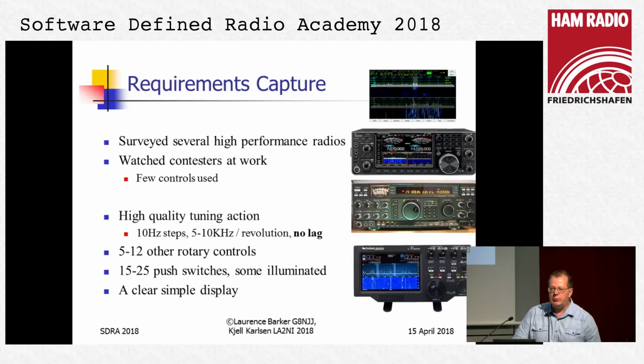So what I did was to watch a contest through the 24-hour SSB field day. And he used almost none of the controls on his FT1000. There's a whole load there. He used the tuning knob, obviously, very occasionally the receiver independent tune, and quite often the variable passband tune to get rid of interference, either at the bottom or top edge of the signal in a crowded band.